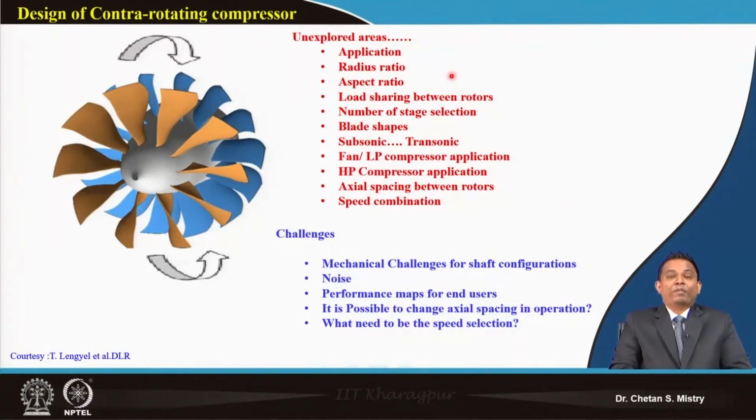Whether we will use this for subsonic application, is it equally applicable for transonic application? People are working on the development of transonic rotors at this moment. There, how my flow physics or flow structure changes is of major attraction. Do we use this for fan and LP compressor application or only for fan application? Do we think of applying that for HP compressor configuration also?